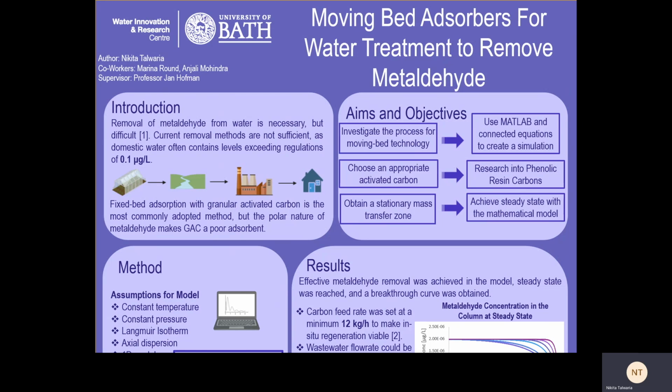This investigation aimed to simulate the same process in a countercurrent moving bed adsorber with in-situ regeneration, achieved using coupled equations in MATLAB. Phenolic resin carbon was researched extensively as it has an altered surface to make it hydrophobic, perfect for adsorbing metaldehyde. A stationary mass transfer zone could be achieved by allowing the model to reach steady state, as it indicates the process can run continuously.